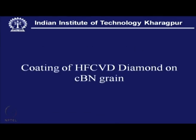Coating of diamond on CBN grain can also be given. In this case, what is going to be achieved is that diamond has good wettability towards many metals where CBN has shown its inertness. So, a coating of diamond on CBN can be a good way of enhancing the wettability of the CBN surface.